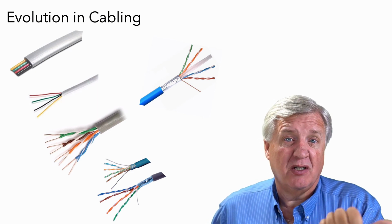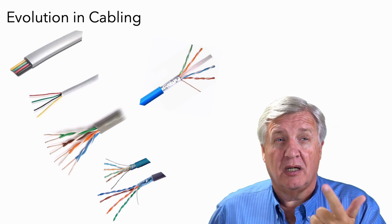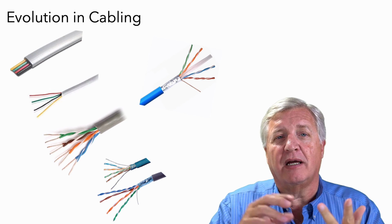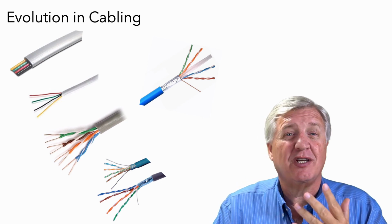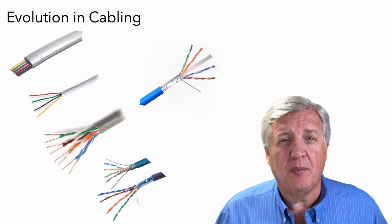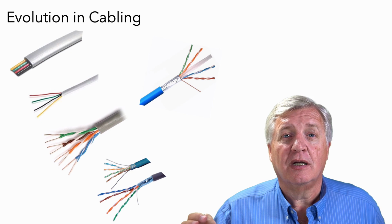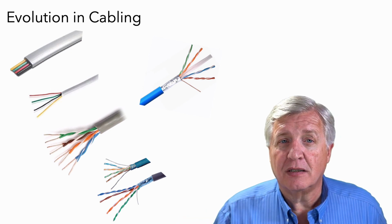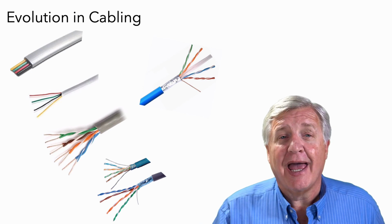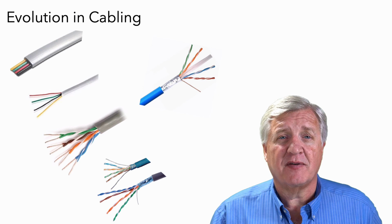The copper is the same. We use the same copper. We use the same RJ45 head. The distances are the same. What we changed were things like pinouts, twist ratios, dielectric that went inside. All of those combined show what we were really changing was the interference, self-interference, a cable interfering with itself. And by getting rid of self-interference, we made it go 1,000 times faster.